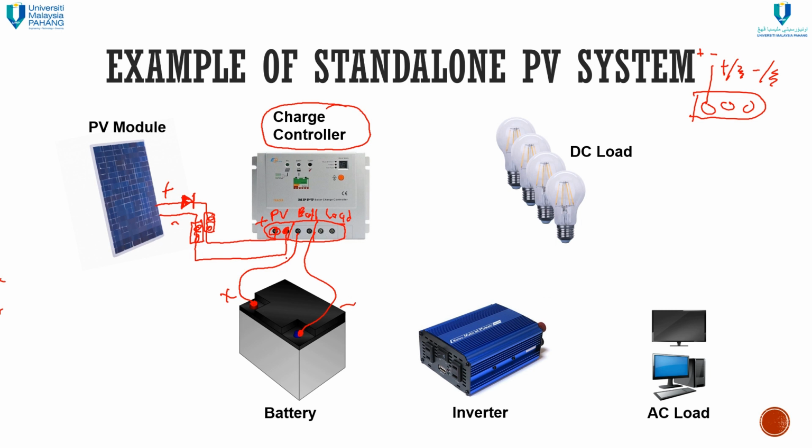So it is better for you to put the MCCB also here. MCCB DC. Okay, DC MCCB. In order to cut, if we keep it off, so whenever you connect cable, it will not create any spark, and there will be less damage, or less risk of creating some spark or arc, something like that.